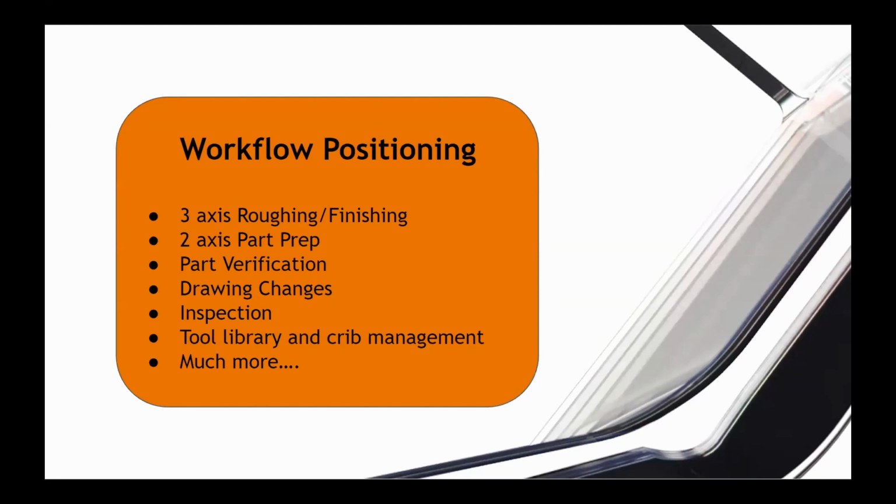Again, like I touched on earlier, inspection points would be another great place where Fusion 360 can be in your workflow. For example, you just had a 15-hour runtime on a certain part, and you were just about to remove it from your machine. We were in a situation where it was difficult to get these parts out of the machine and then put them back in to realign them, right? So a quick little inspection toolpath that uses the probe inside my machine at the end of all my machining goes around and probes a couple of features.